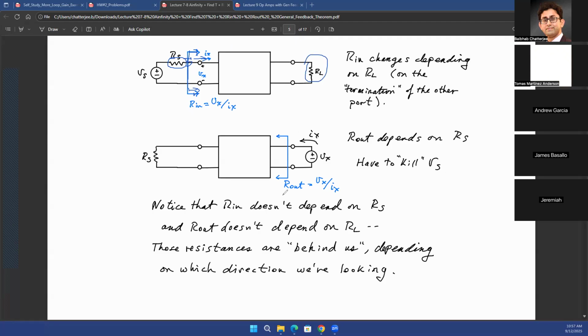Similarly, on the output impedance, if you're looking at the output from the output side toward the left, if you have a source resistance RS, for example, the same source resistance of the voltage source, and the value of that source resistance changes, that will have impact on your Rout. But the load resistance does not have any impact on your Rout, because again, remember Thevenin, you disconnect your RL, you remove your load resistance, and then you start measuring your Thevenin equivalent resistance, right? Because looking at this terminal, if you're trying to look to the left side, whatever is connected to the right does not matter. Because you're only interested in what you see on the left side of this output terminal, not on the right side.